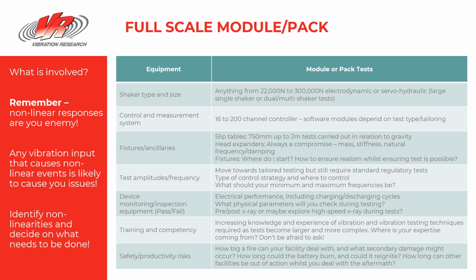Obviously, training and competency, doing big battery packs, you've got to really increase your knowledge and experience on vibration testing and actually understand the physical things that are going on in relation to your test facility, and know your test facility in a lot more detail than you would with a little cell-based vibration test.